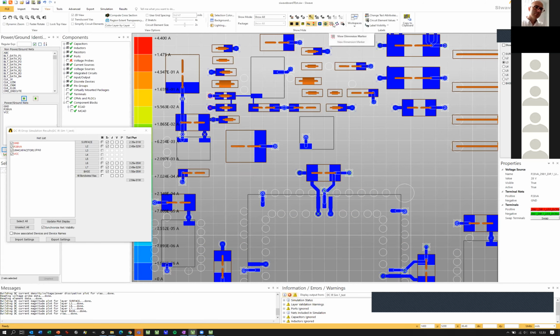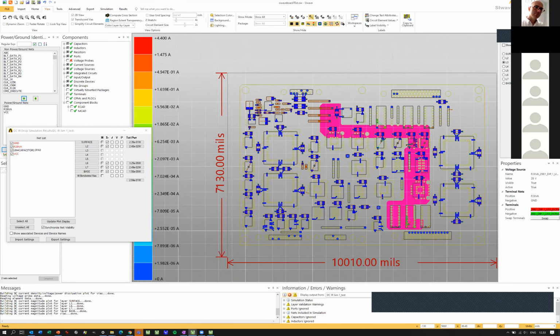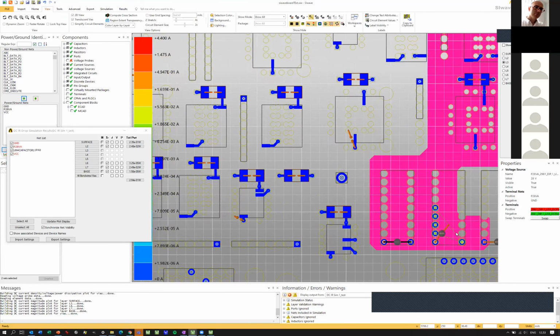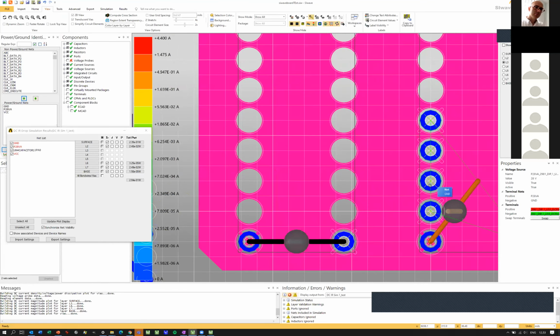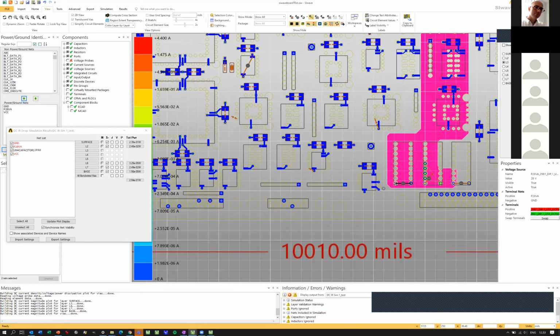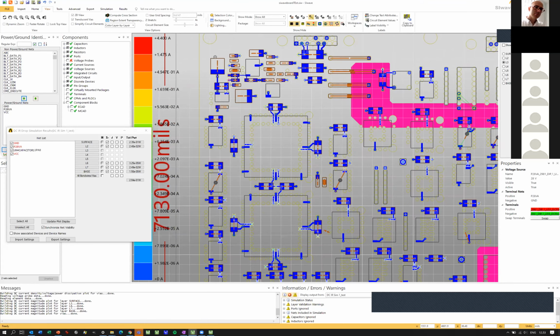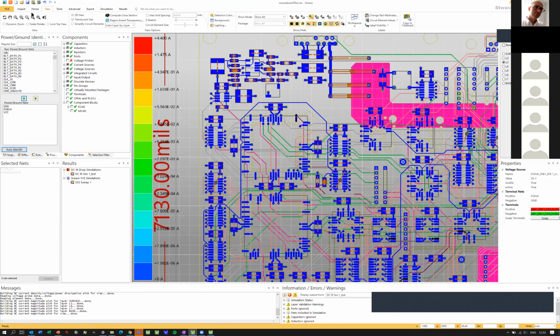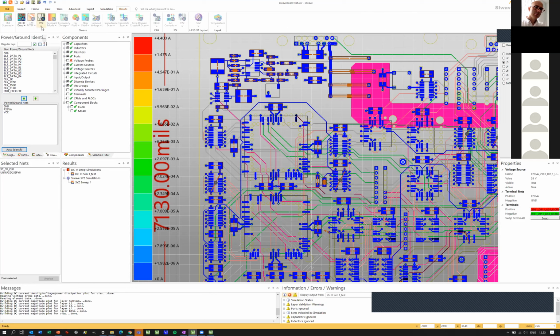Okay, no temperature plots. Okay, I'm looking for via current. Oh, okay, sorry. Yeah, it is. But this blue color means it's still reasonable. I'm looking for red vias, but I can't see any real problems here with this one. Okay, but that's more or less the basic things, and then we can go and get something more and plot the iceberg power map.